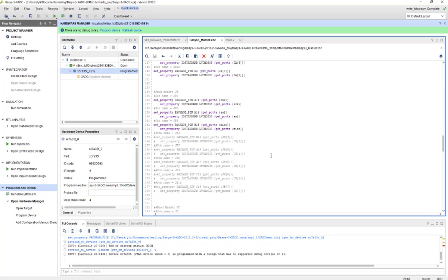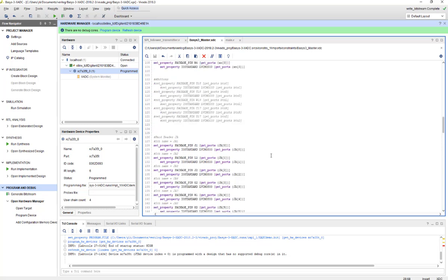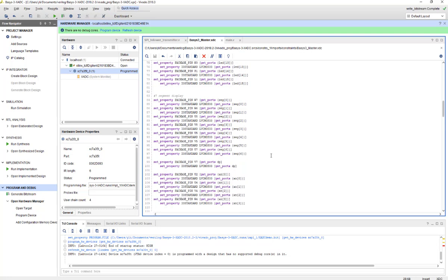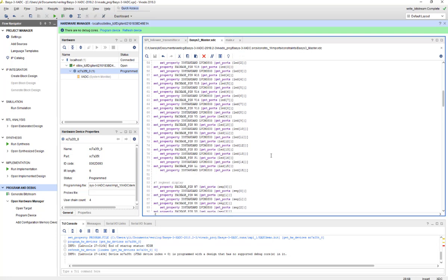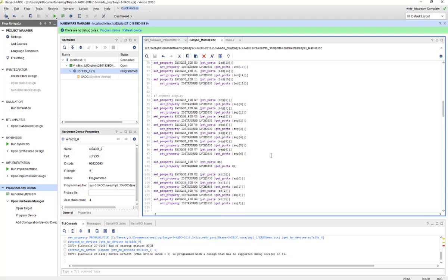So for the JB ports, I use JB1 as SCK, JB2 as SS, JB3 as MISO. For other things, these SEGs and ANs are not really used, but you can use them because they're from the example. It's really nice. It's showing a decimal number on the 7-segment display. It's really satisfying to watch, because when you change your power supply's voltage, you see 0.6 volts, right? It's displaying somewhere around 0.6. It's pretty accurate. You can use that to verify your readout.